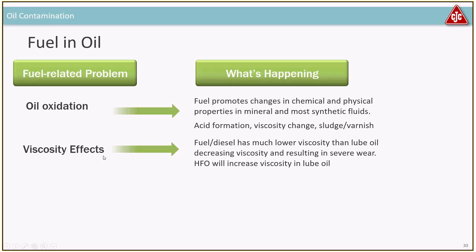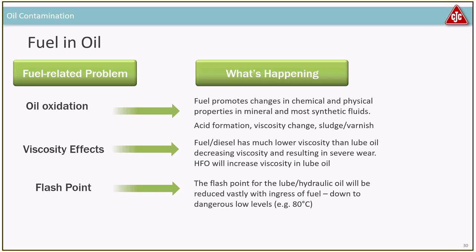The biggest problem is viscosity, because fuel, diesel for example, has much lower viscosity than engine lube oil. So you'll be decreasing the viscosity and creating really bad adhesive wear in your bearings. If you're running the engine on heavy fuel, you'll see an increase in viscosity, which is also bad. Your flash point will also be harmed. Oil will mostly have a flash point of about 240, 250 C. What's that in Fahrenheit? I think 400 or something like that. But it can get very, very low if you have too much ingress of fuel.